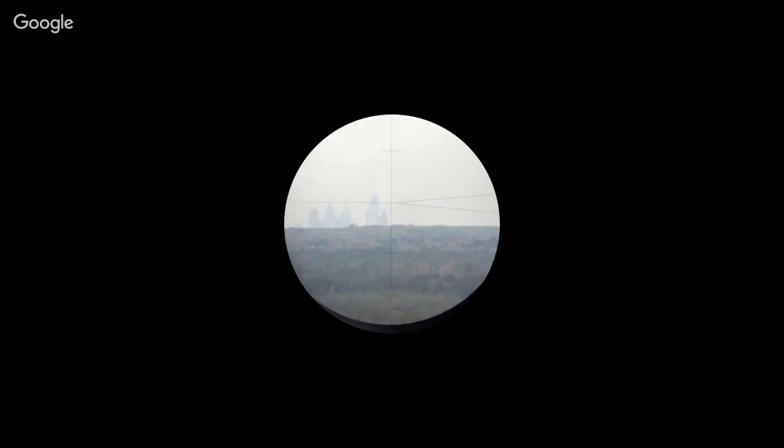A lighthouse is a critical navigation beacon. People need to know where it is on that nautical chart. How did it get on the chart? Geodetic triangulation. So I can take those positions, put them in my software, or even just write them in my book if I'm using my old T2. I can sight one lighthouse, compute the angles to the others, and literally turn to it and find it. There it is. Most of the long distance stuff I've done has been all angular.